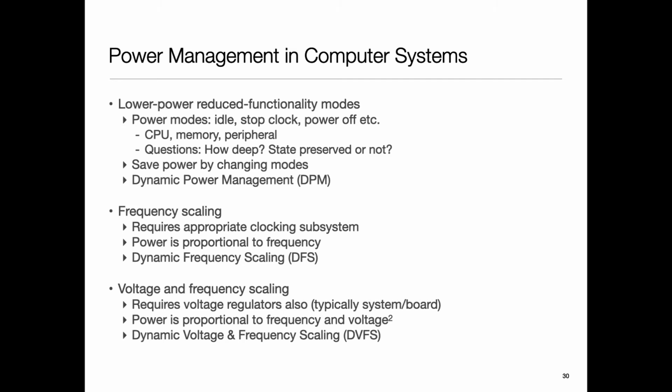Frequency scaling alone lowers the power because I have more time, I'm spreading the energy over a longer time, but it's not helping in terms of my battery life, not to first order. Whereas this strategy lowers the energy taken also. So this is called DVFS, or dynamic voltage frequency scaling. This came first. If you go back, dynamic frequency scaling systems probably emerged in the early 90s, and dynamic voltage frequency scaling systems emerged in the late 90s, about 10 years later.